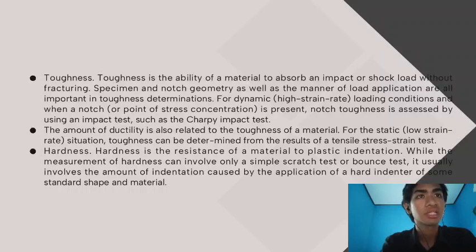When the stress intensity factor that describes the state of stress at the tip of a crack of given size and geometry exceeds the plane strain fracture toughness of the material, crack propagation will result.